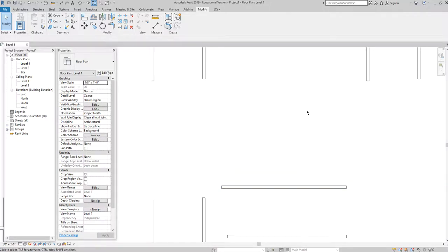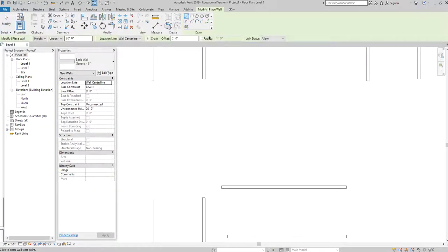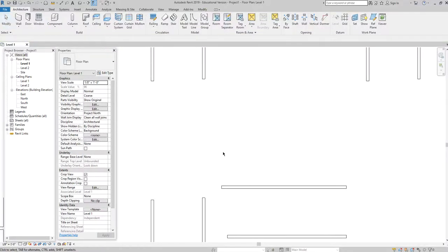And you're like, wait a minute, I think that we sort of already talked about that, right? When we were creating walls, and we did, right? But that offset was built into the wall command, okay? So this command is just a standalone offset, which means I can do it to walls, doors, windows, furniture, right? Anything else. There is, though, the built-in offset command into the wall command and other commands. So, for example, I'm going to go back here to architecture, wall, and you'll notice offset is one of those options.